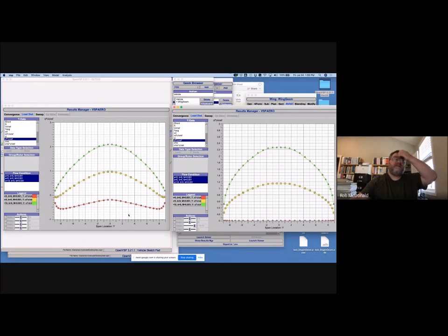So here are some fascinating things that they don't teach you about aerodynamics until you really know what you're doing. This is some good stuff. This red curve is what we call the basic lift distribution. It's typically the lift distribution of a wing at 0 angle of attack. We also have the concept of what we call the additional lift distribution, which is the delta, the change in the lift distribution as you change angle of attack.